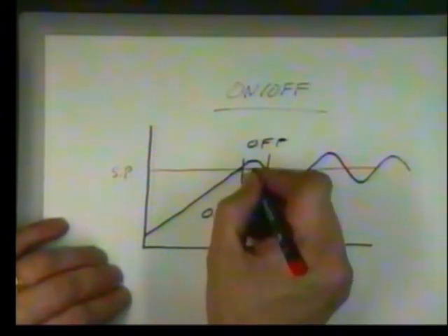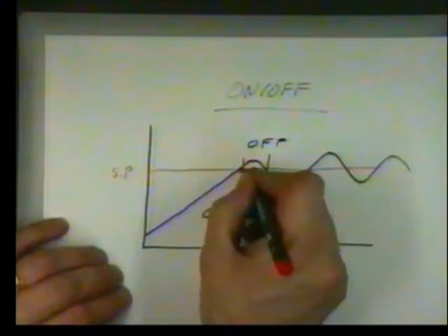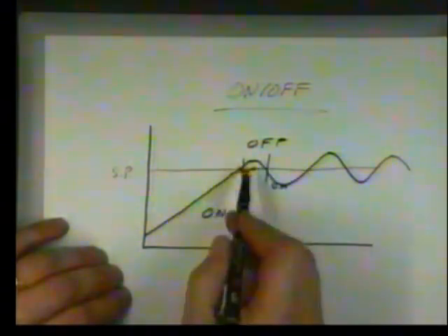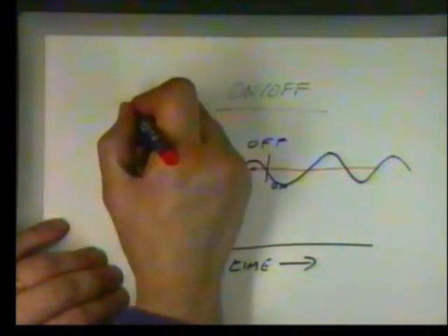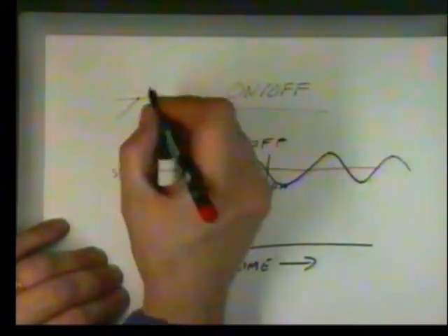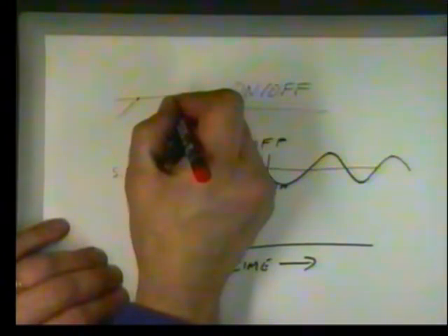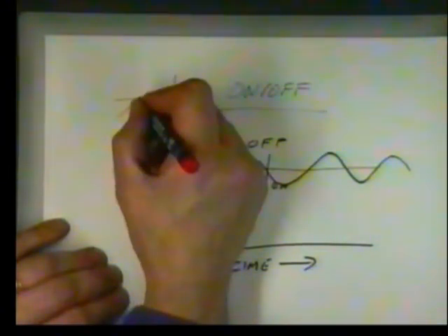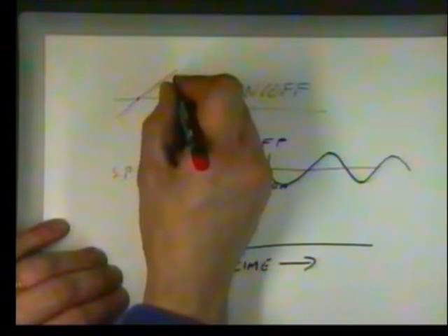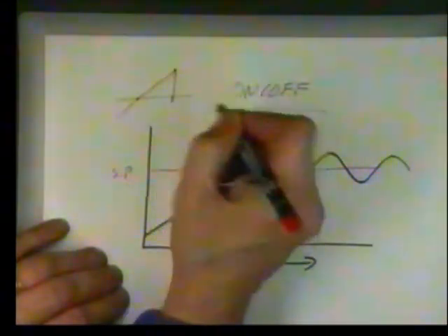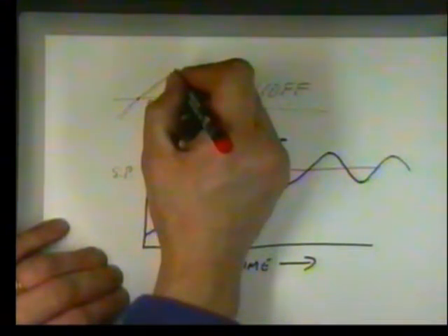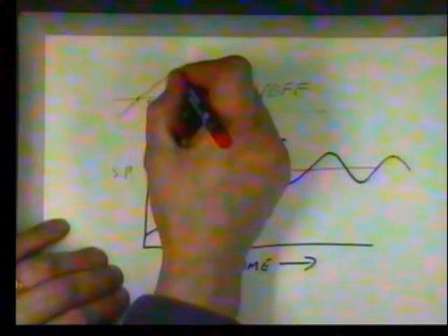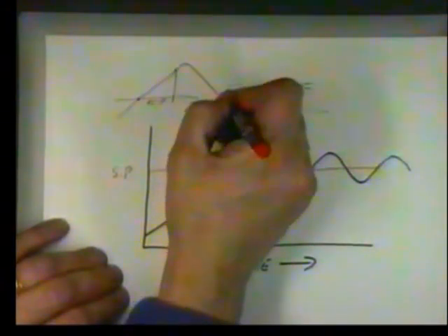We always realise we've overshot sometime after the real event. So even though we have reached our set point, our processor doesn't realise it till sometime later. So we will continue driving heat into our system until we realise we've done it, and we've switched the heating system off, and that command has gone to it, and the motor's turned off, and everything is turned off. Only then will we fall.